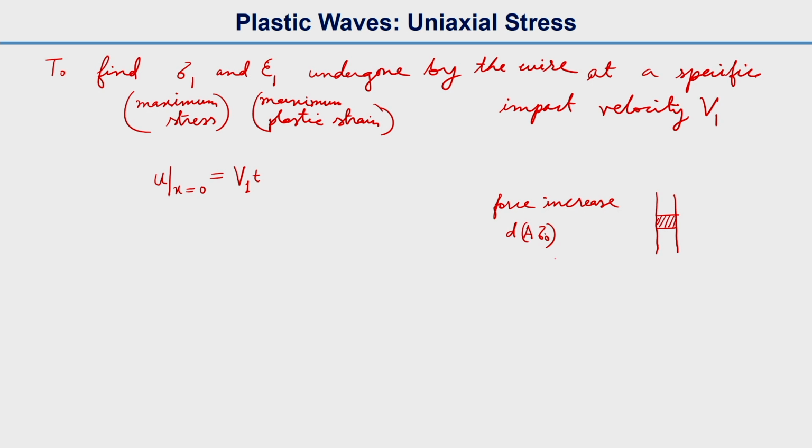We will call it the force increase, because as the plastic wave or the elastic wave is moving upward, let us say this is the wave direction, the force will increase from the bottom part to the top part, and we are taking a small element dx here, and we assume that this force increase travels the distance dx in time dt.